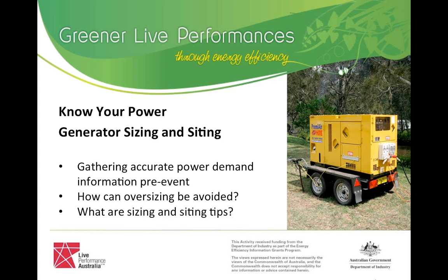I think it's good to start off that a generator runs at 1500 RPM. So you have a base fuel consumption, just if it's chugging away without load. So your biggest benefit is to size it accurately, say running at 70 to 80% of its load. There you get the best bang for your money in terms of fuel consumption.